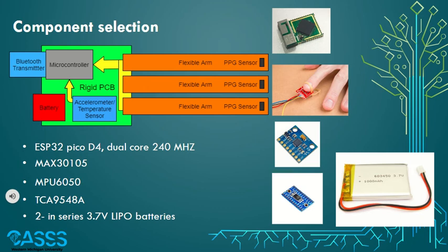For our PPG sensing, we chose the MAX30105 chips. The reason is that those chips themselves sample the photodiode very quickly, at megahertz level speeds, and store the data in a FIFO that we then pull with our microcontroller using I2C, which is a very nice protocol to use for our system. And we chose the MPU6050, which is our inertial measurement unit. It integrates our accelerometer and our gyroscope, and it also has a Hall effect sensor in there to help with our filtering.